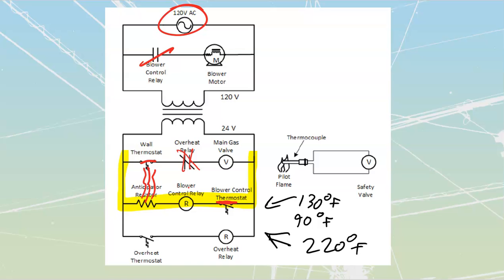It's a safety on our system. Your module lists a couple of ways that these things can fault. Room thermostats that are stuck closed. If I've got a blower motor that is refusing to run, the motor is shot, or the belt that goes from the motor to the fan, most of these are belt driven, has been thrown off or broken or something like that. Or if I have insufficient airflow. Any one of those is going to allow us to get to way too much heat inside of it.